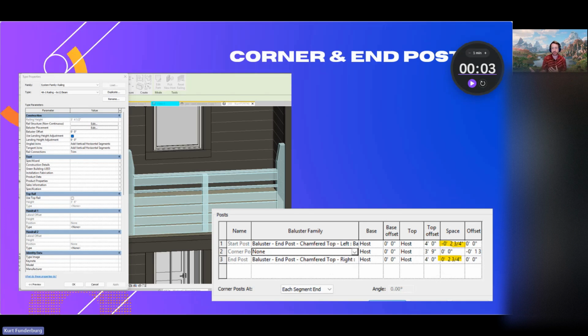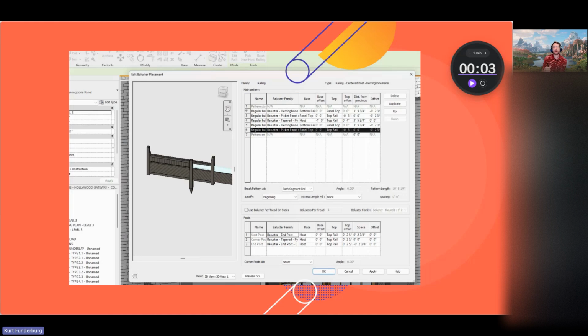So again, this is where the math comes in, where a lot of it is halving the value to understand, because things are built off of the center of the baluster. So a lot of railings is what's the half of that value, and then I need to half it again, and then I need to half it again to understand how it sits symmetrically within each thing.